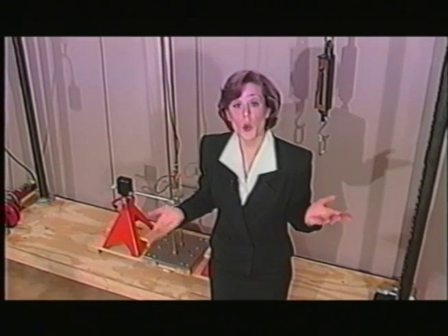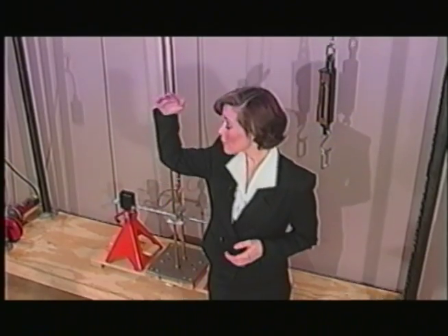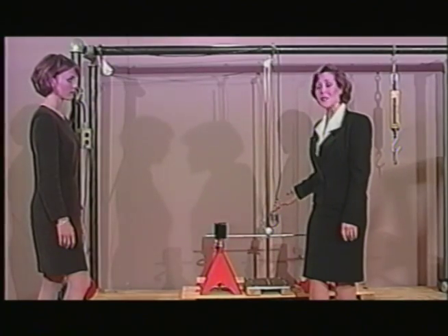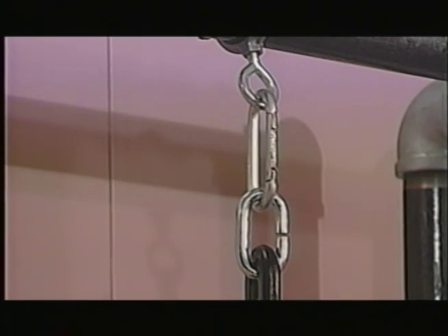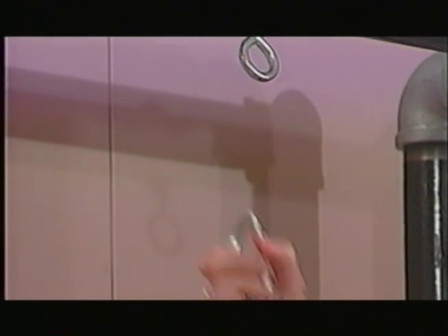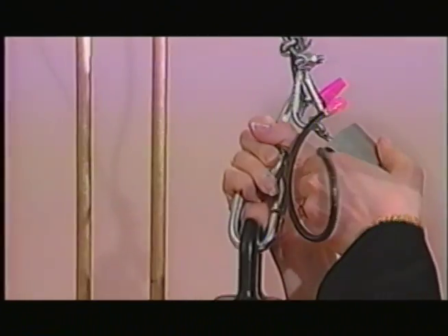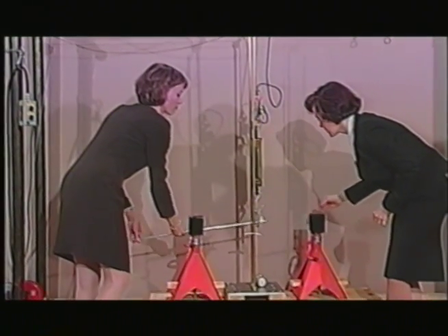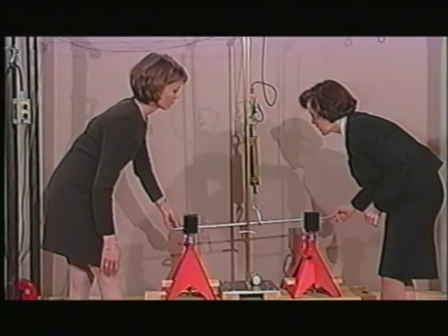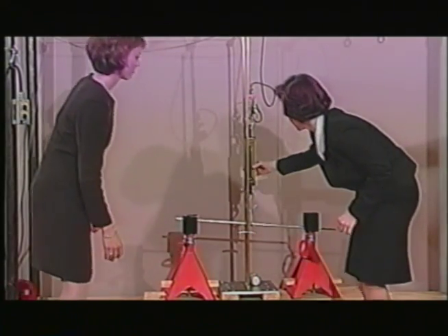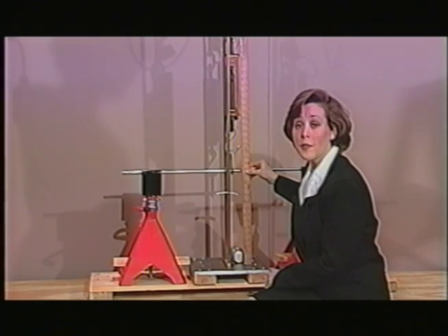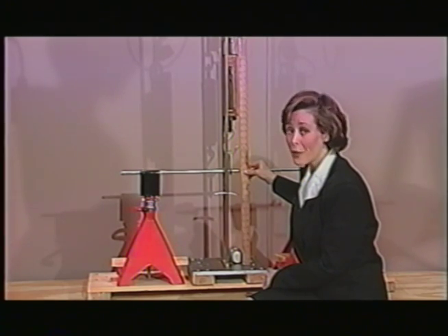For that, we will reverse the experiment. May I have a volunteer from the audience? We will use the winch to pull up on the bar until the deflection is about the same. If we insert the scale in line between the cable and the bar, it will read the same force that it took to bend the bar when the weight dropped on it. Okay, in the bar. Okay, go ahead and take it up. We need to bend the bar 0.156 inches, which is between 1/8 and 3/16 of an inch.